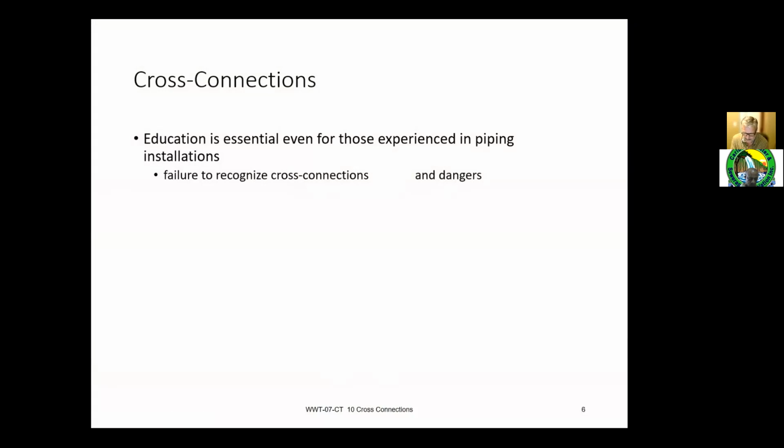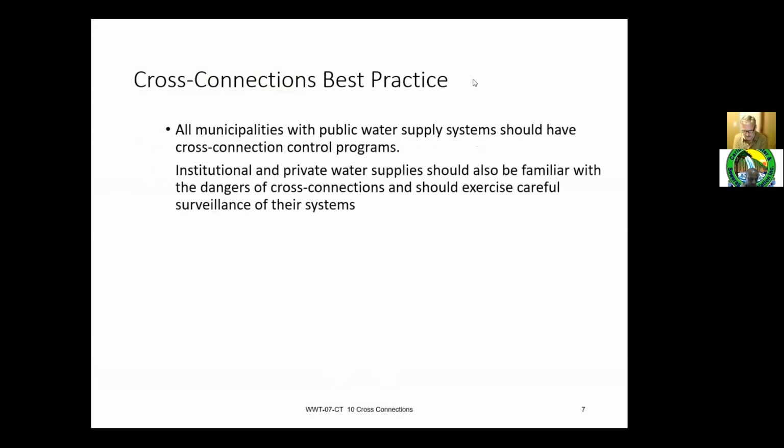Cross connection backflow is a certification program here for testers. I'm not sure if they have the same program in your areas. Recertification is done every 2 years. Many facilities, using best practices, have a cross connection control program. It's your best option. For us, anytime there's a new pipe going in the ground, or work being done on site that requires lines connected or repaired or new lines installed, the cross connection person is involved in the loop of communications. They don't necessarily run out and inspect every line that's installed, but they have an overview and can sometimes provide information that's needed.